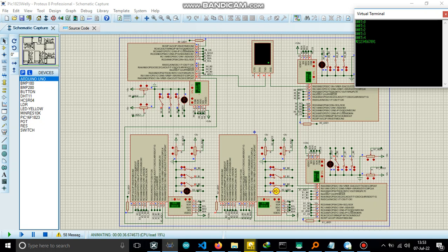Of course, we can also use the microcontroller we are using for debugging, as we will be connecting it to our computer and we will be able to see. In most cases in debugging, we want to use the UART to send data to see what is happening, and it won't have an effect on what is happening to the modules in the testing phase. If I write, for example, my name, that data will be sent back and my name will come back there. But because that data doesn't begin with the #2 and end with the $ sign, it doesn't matter.